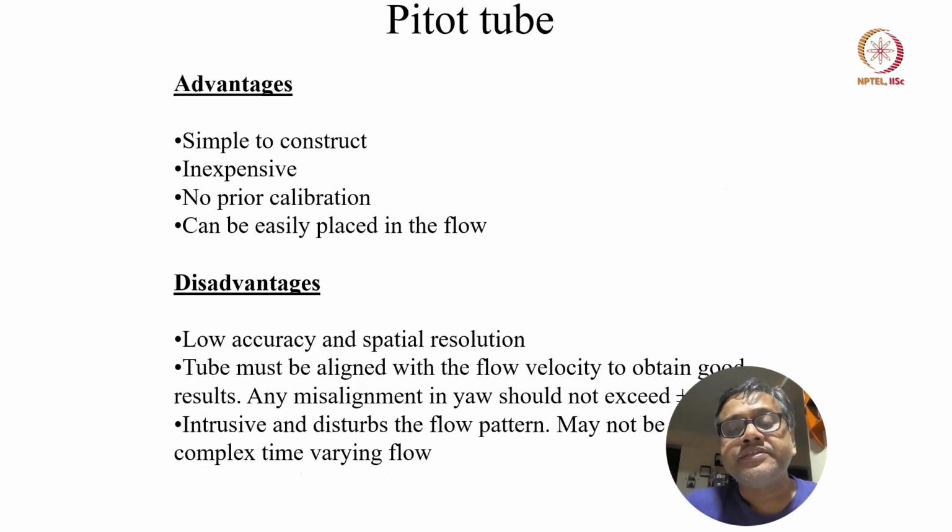All right. So the advantages are that pitot tubes are very simple to construct. You can construct it yourself. All it requires is a central hole, and you need a bunch of side holes, tappings, which are perpendicular to the flow direction.